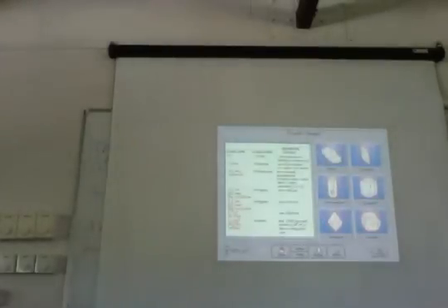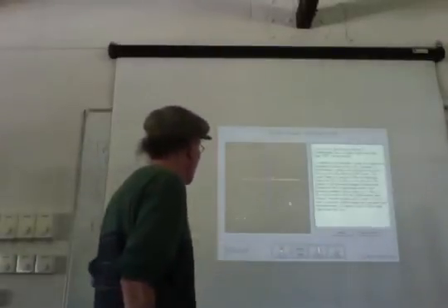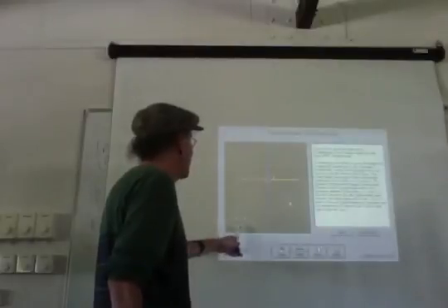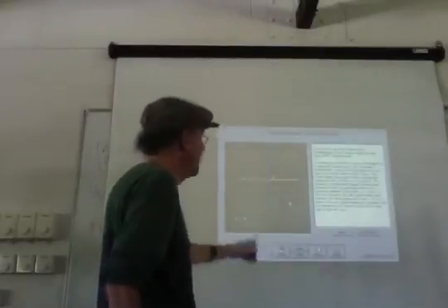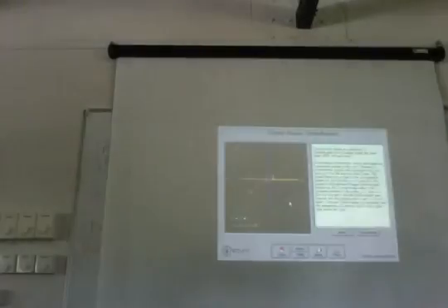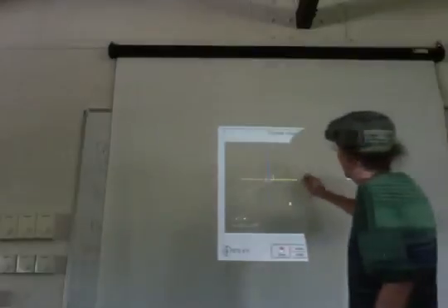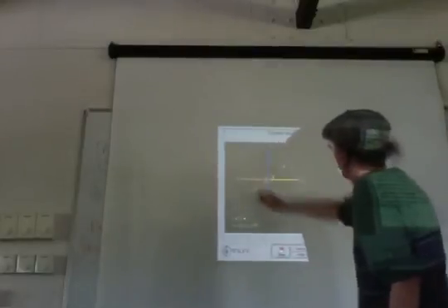Now let us go to the orthorhombic system. In the orthorhombic system, A is not B and is not C, but alpha, beta and gamma are always the same angle, and that is 90 degrees. So the crystals in this system are referred to 3 crystallographic axes of unequal lengths that make angles of 90 degrees with each other. Here you have again A plus, A minus, C plus, C minus, B plus, B minus.